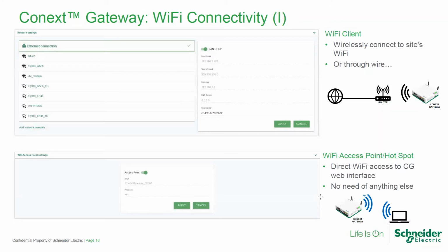So you have a commercial system which is supplying a facility that has a control display center, which is able to pull and obtain information from the Modbus master, in this case the gateway, and display it onto your own interface, right, on your factory or your industrial plant, etc. So all that information on those protocols is freely available at the Schneider Solar website, and there is very detailed information in each of the manuals on Modbus protocols for developers, right? Developers as in people that develop these polling and communication applications.